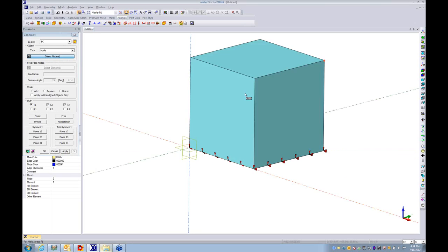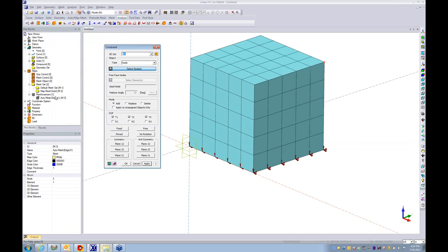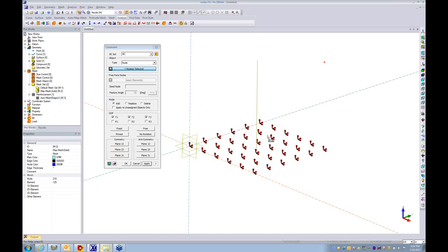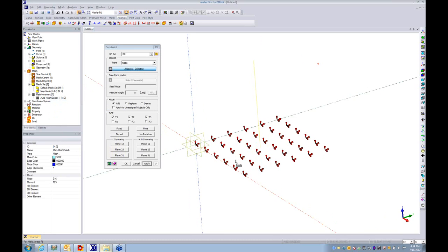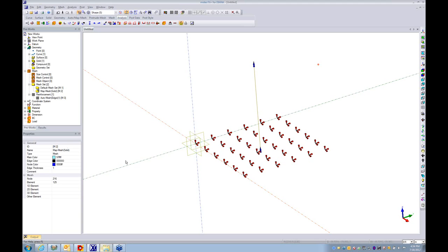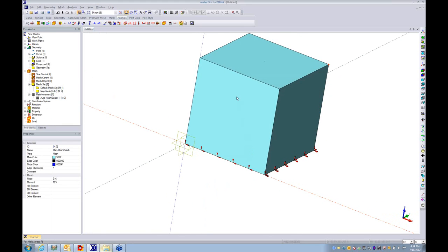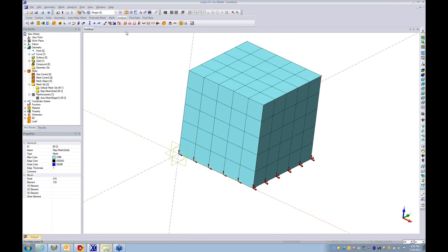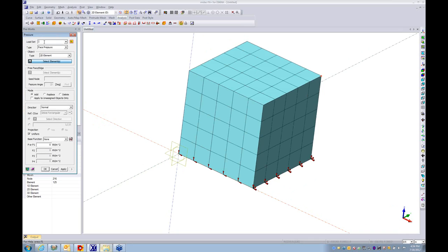Also, I'm gonna assign rotational degrees of freedom, or constrain them, to my beam. So I select both ends, and only rotational over the Z. Show, so we have everything. The next one is imposing force. I'm gonna go to the pressure load, 3D face.